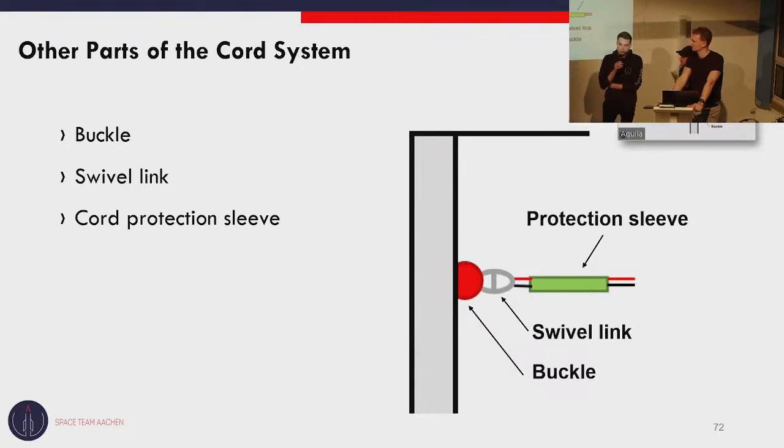It is not actually a bag, but more a long sleeve. This is a design that was inspired by paratrooper parachutes. So before the main parachute slips out of the deployment bag, it is completely stretched out. So the problem that we had during the Carl 2 flight was that the main parachute got entangled on the cords that were supposed to hold it. So here in the Aquila rocket, the improvement is that the parachute sleeve is long, and the main parachute canopy is fully stretched before the parachute inflates, rapidly reducing the time that is there for entanglement to happen.